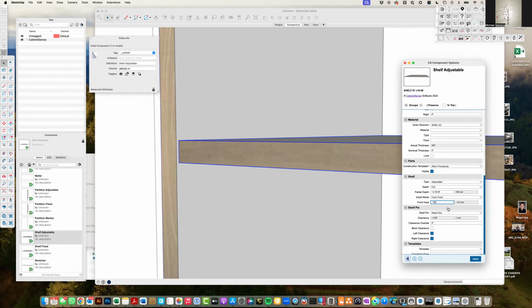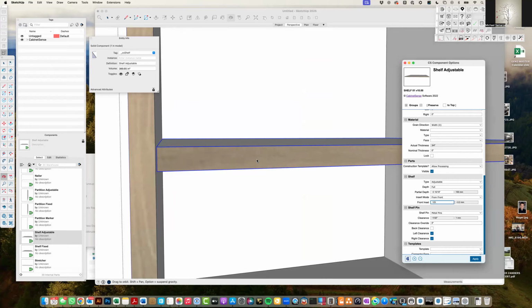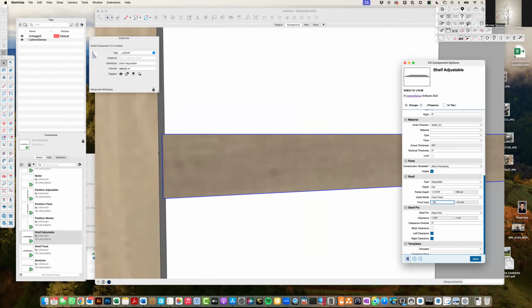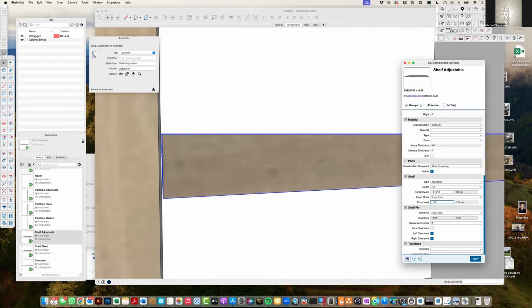All right. And the other setting that we have is on the edge. Right now, by default, it's 1 millimeter. Do you have any preference here as to how you want your gap to be? This setting is per side. Usually we'll undersize the shelf by an eighth left to right, which would split to a 16th per side. All right. Very good.